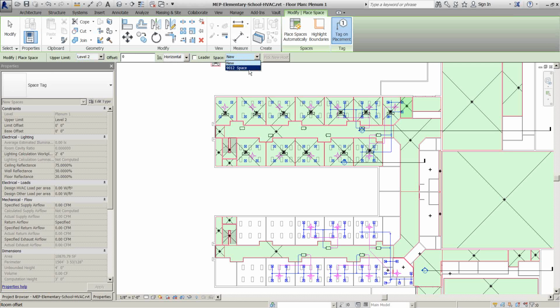So I could have gone in there and customized it, and in fact, I can have a whole list ahead of time. It's another one of these tips that will help make Revit a little faster, if it applies to you. It may or may not be useful in every project, but let me just throw it out there. Say you do a lot of hospitals, or a lot of hotels, or a lot of similar projects. I can have a spreadsheet type of list in Revit with all my rooms. Maybe I know ahead of time that there's going to be 5 conference rooms, 120 guest rooms, 2 laundry rooms, 1 IT server room, 5 offices, whatever.